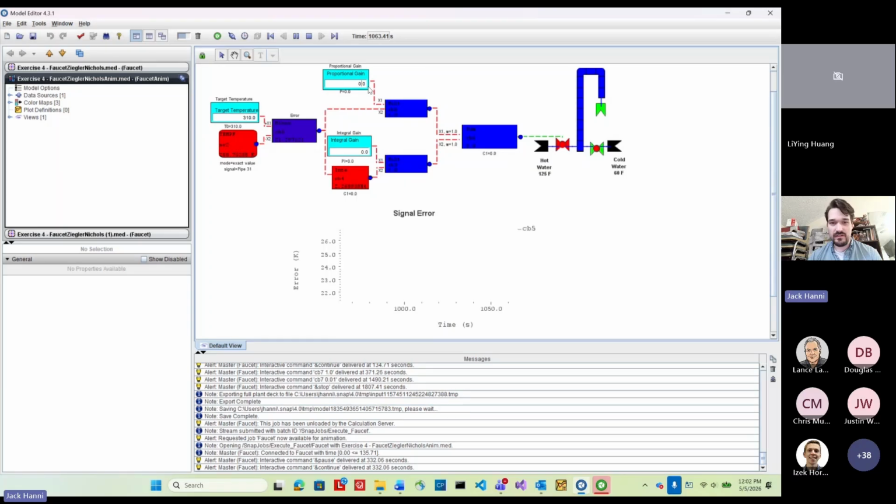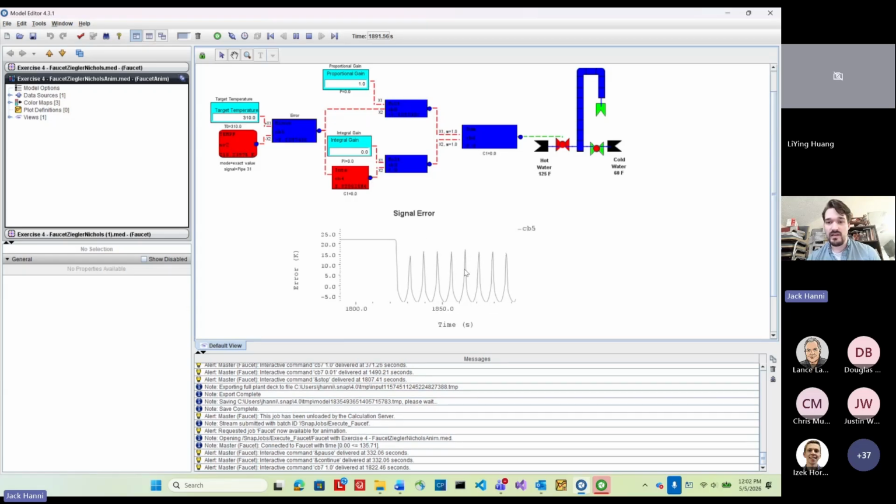So yeah, with Ziegler-Nichols, it is kind of hard to determine what order of magnitude is correct to start at. Because we did the step method, we know that it's roughly on the order of 1/100th or 1/60th rather. But if you didn't know that, then you might just start with 1 and you'd see that it's oscillating at roughly constant amplitude.